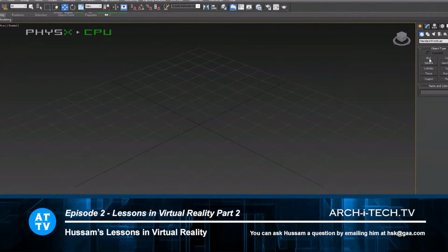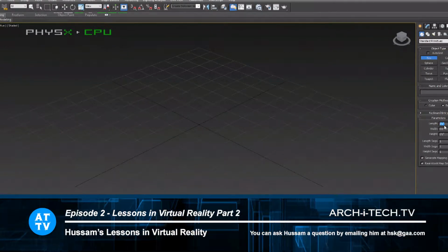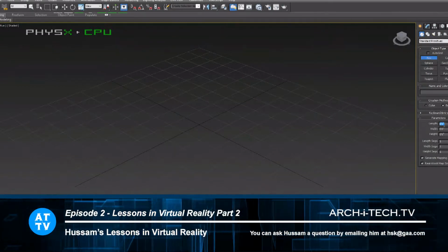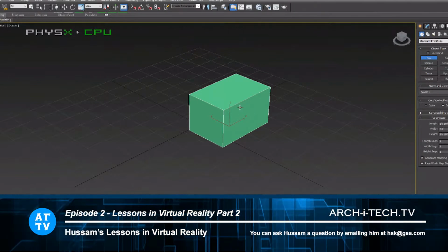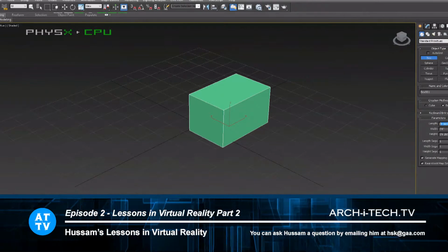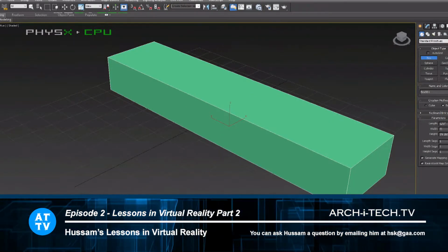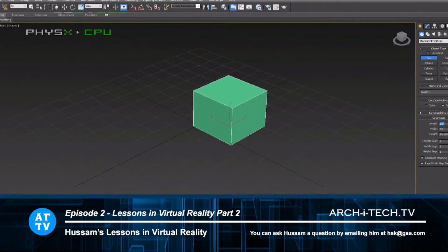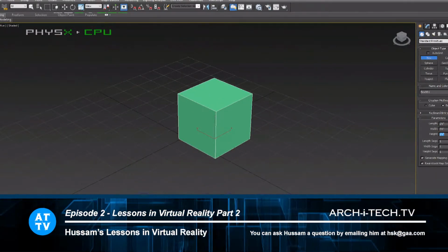You will notice that if you create any 3D object, the unit will change to feet and inches over here, so you can put whatever dimension you want. Or you start creating your 3D object in a viewport, and then go to the parameters and put 2 foot by 2 foot over here. And then you will have a box that is 2 foot by 2 foot by 2 foot, like that.